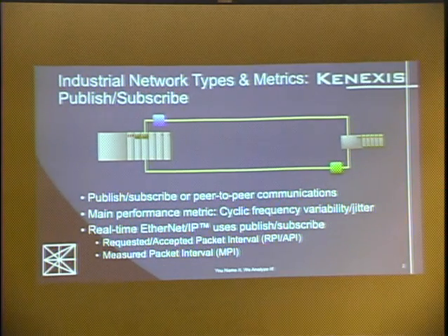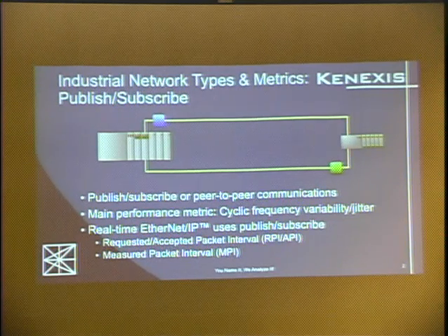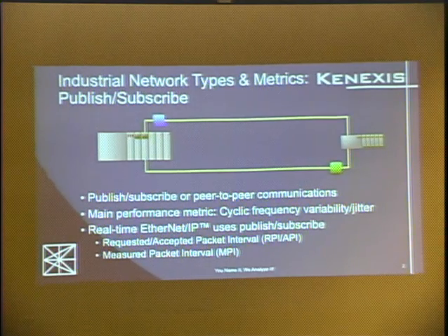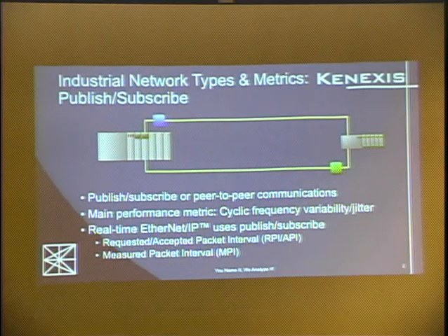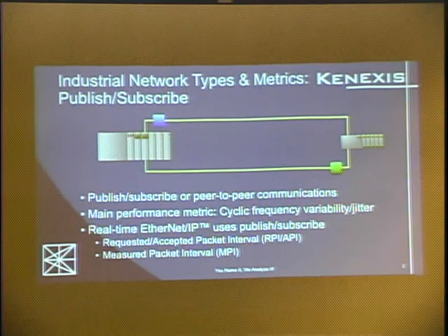And generally there's two sort of modes where most industrial devices live. One is publish and subscribe, and one is command response. Not unheard of in the IT space, but they're very deterministic in the industrial space. So making sure that that communication is precise and comes exactly when they need it is very important.